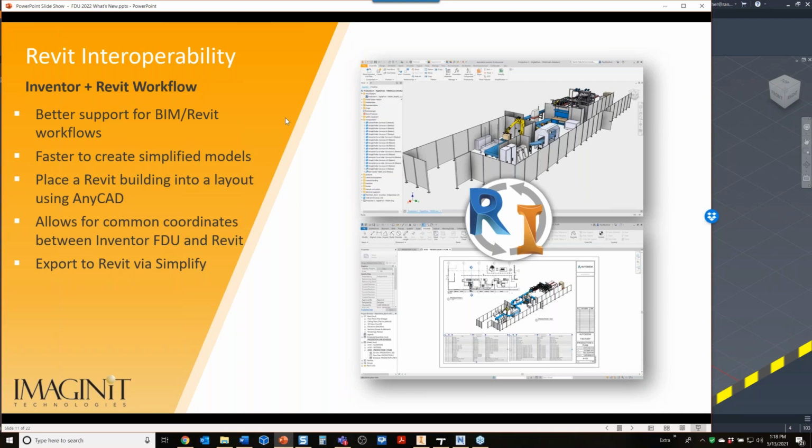And what this means for us as factory utility users is, hey, the first thing I can place in my assembly now, in my layout, is a Revit building. Then I can establish my layout positions and I can go start dropping in machines in context of that building. Think about working in context of a point cloud, all right? Or working in context of a DWG underlay. Now we can actually work in context of the Revit model itself.